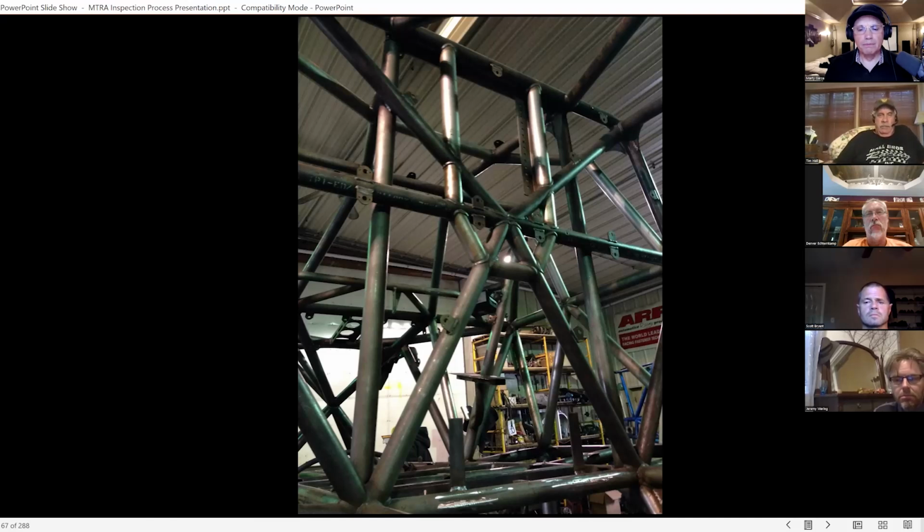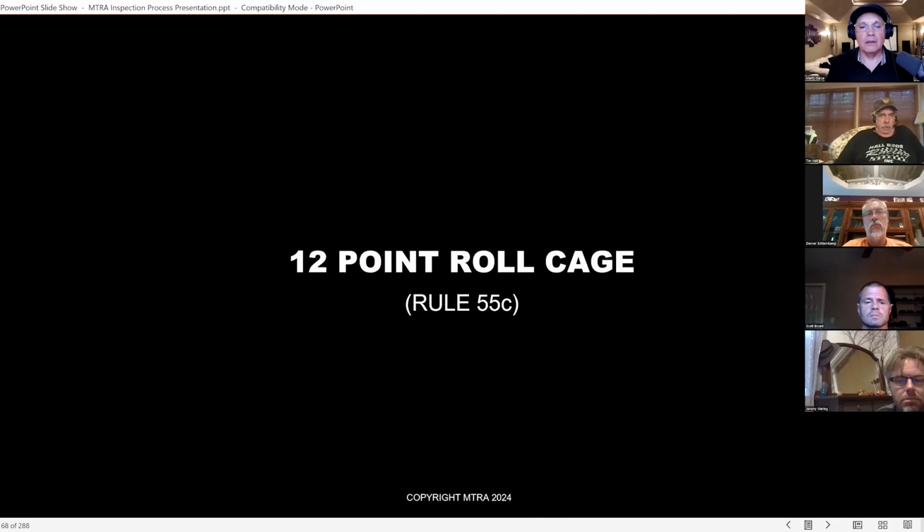That's why this is being reinforced so rigidly with the new trucks. The idea is that if the cage collapses, it takes the seat down with it, rather than the seat staying in place and the cage coming down and potentially getting into the top of the driver's head.